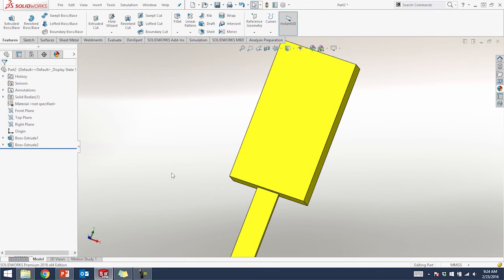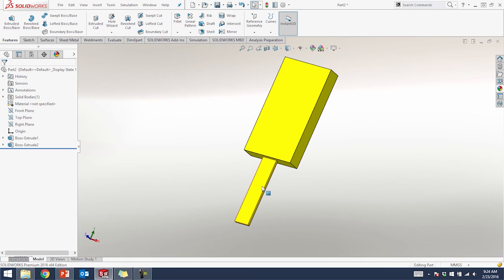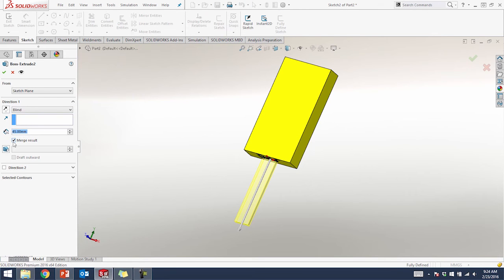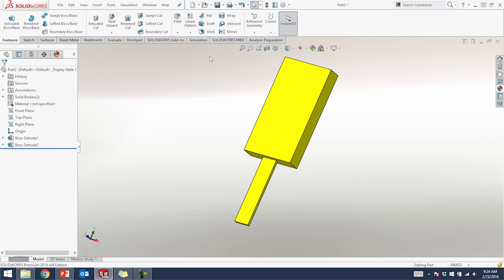Now, since I'm creating an ice cream bar, I'm going to use wood on this bottom portion, and I'll use a black color up top for chocolate. I want them to be two separate bodies, and I'll show you why. To create two separate bodies, I'll unmerge my results and head back over to my model.